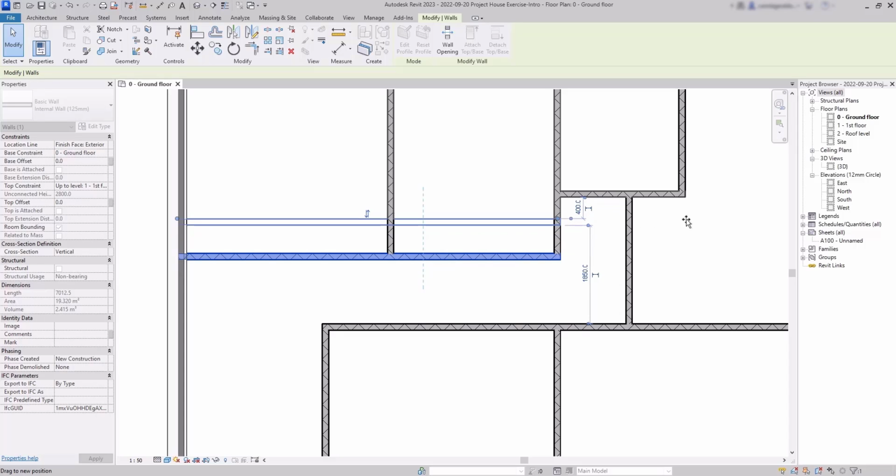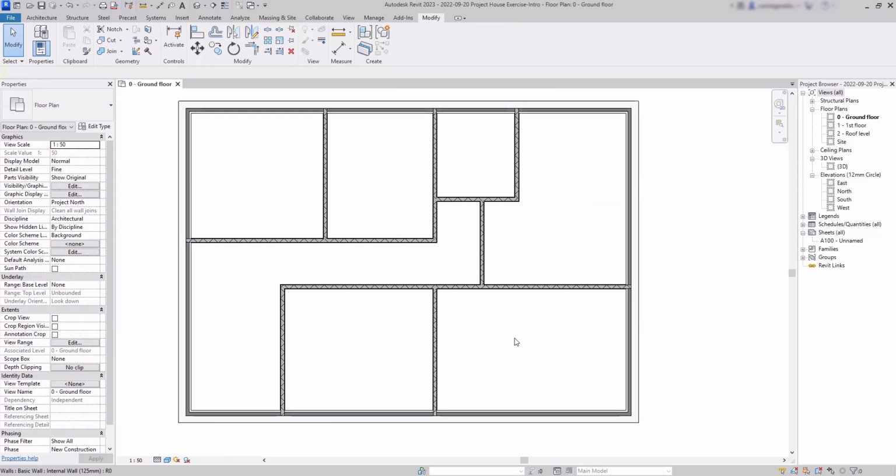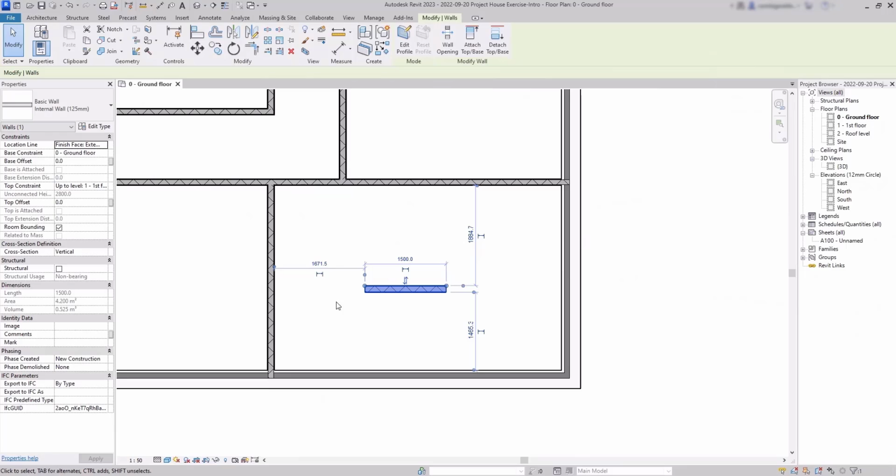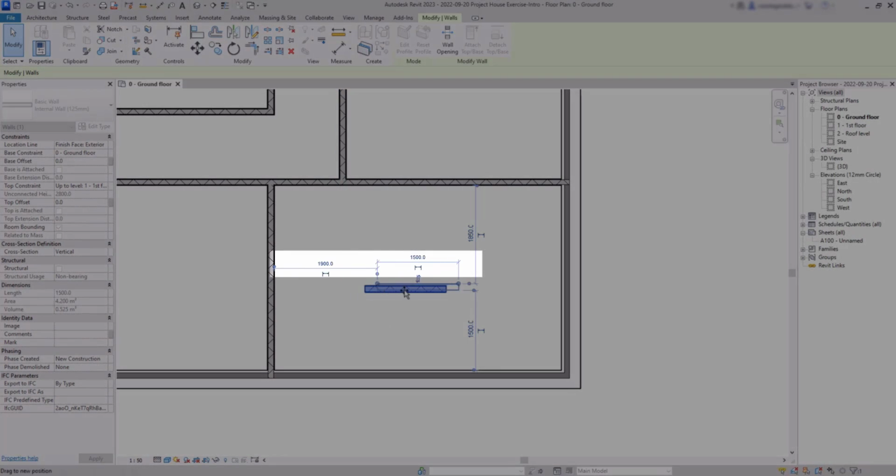Because if you try to move it in the same direction, Revit doesn't let you, because it's constrained with the vertical walls. That's why if a wall is vertical, we move it to the left or to the right. However, if a wall is isolated, it has no constraints, and you may have temporary dimensions along the same direction.